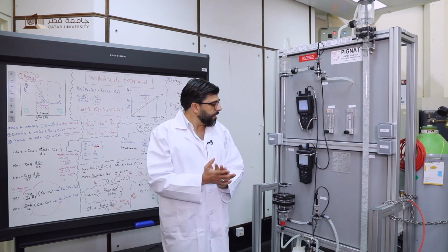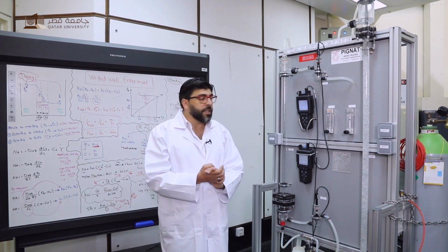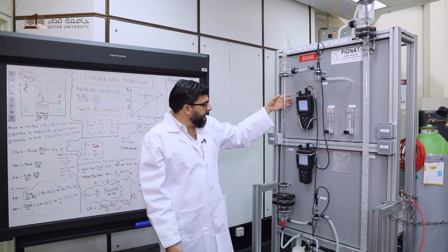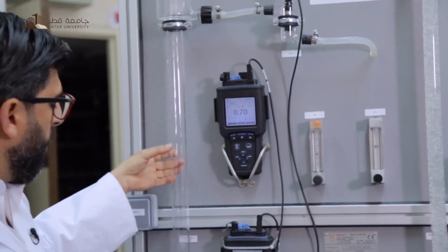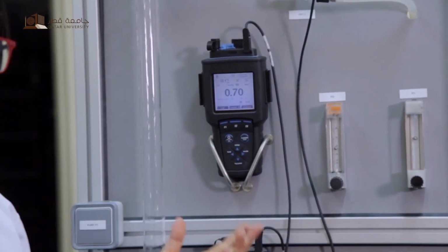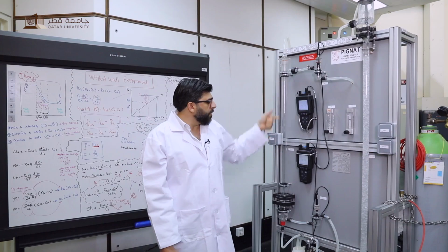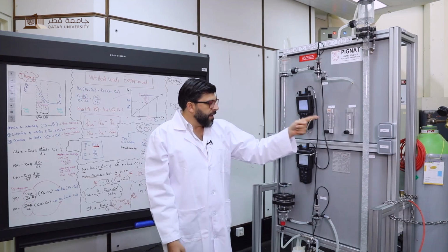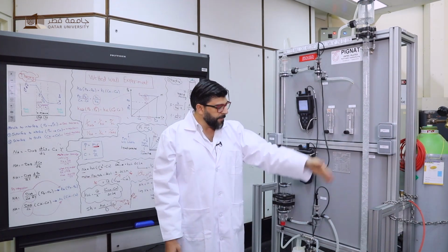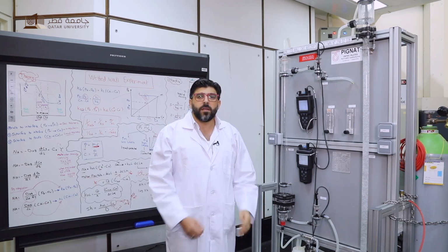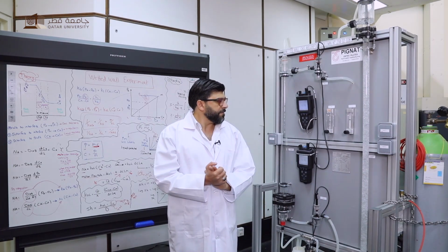So that's it. The first important thing is to ensure you have a film. If this film is not a continuous flow through the column, that means you don't have the correct area, πδL. So you have to ensure it's continuous, and you have to check the data and the purging, of course, the nitrogen purging. That's it. And thank you so much.